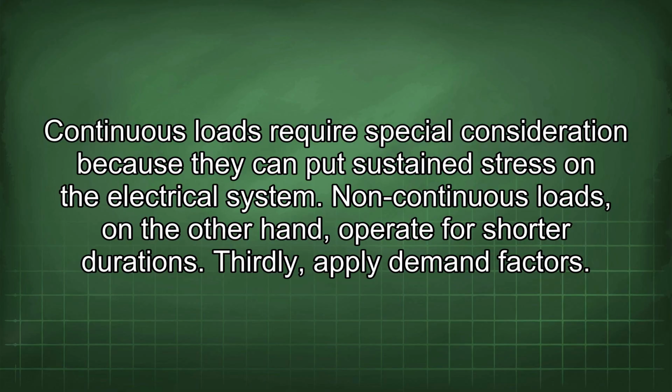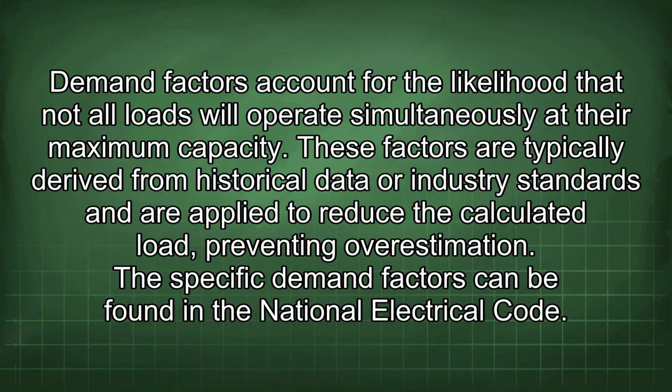Thirdly, apply demand factors. Demand factors account for the likelihood that not all loads will operate simultaneously at their maximum capacity. These factors are typically derived from historical data or industry standards and are applied to reduce the calculated load, preventing overestimation. The specific demand factors can be found in the National Electrical Code.